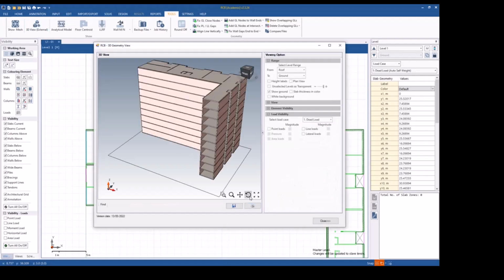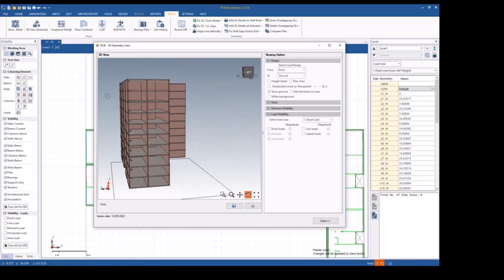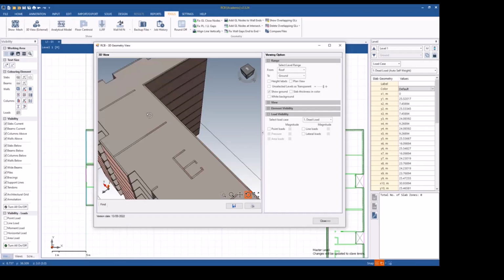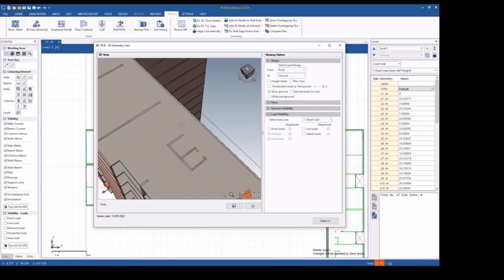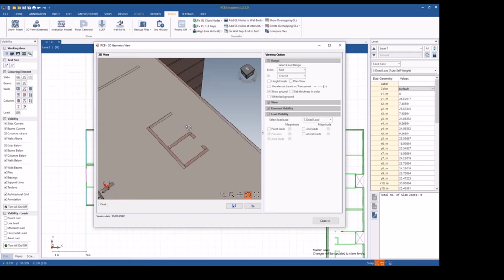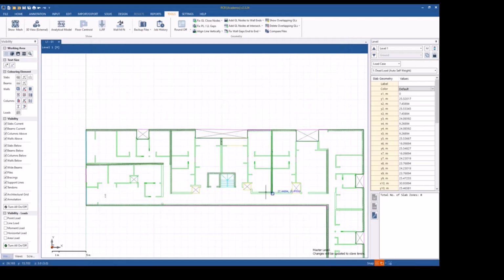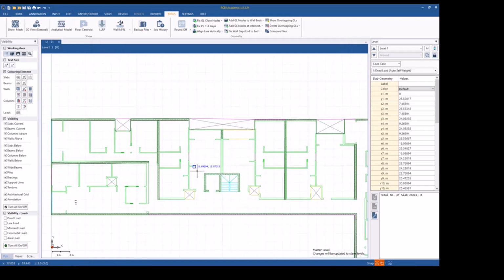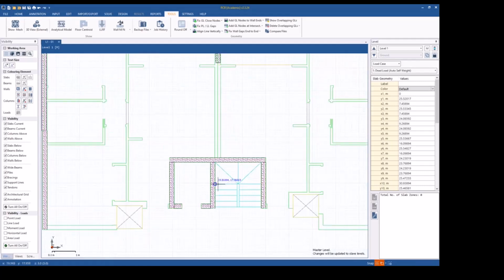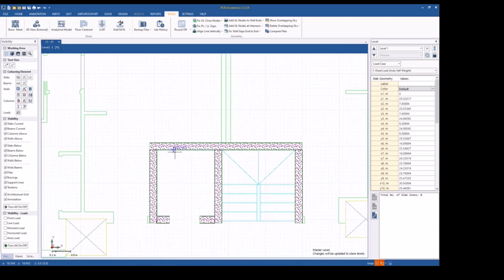See, the slabs are drawn for all the levels. Right? Now, again, I will have a question asking me what we're going to do for the voids, especially for the core voids. This is our main topic here. And there are also other voids in the building. We will define another slab, and we will give it a thickness of 0. The thickness is going to be 0.